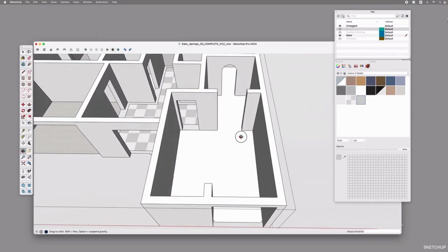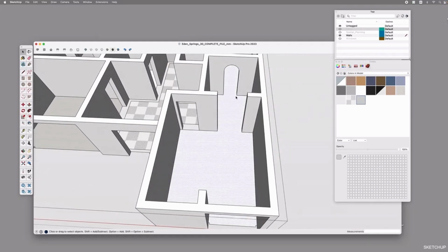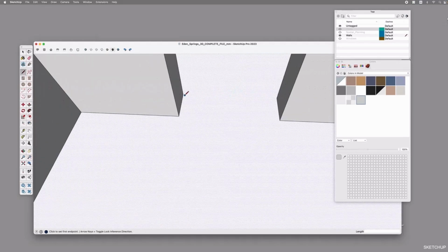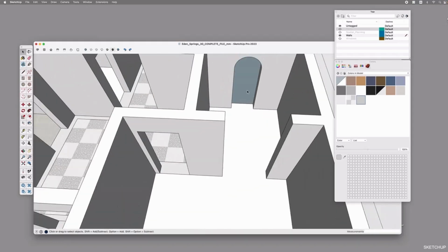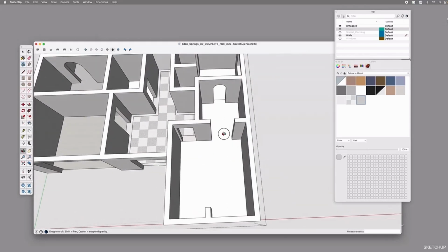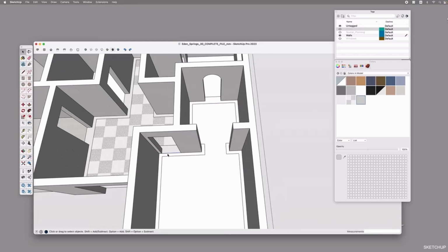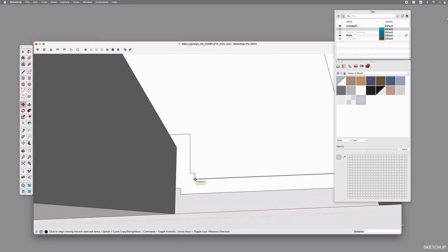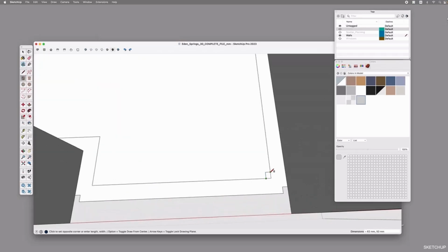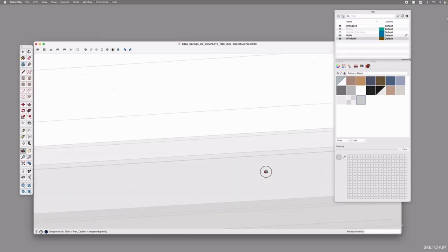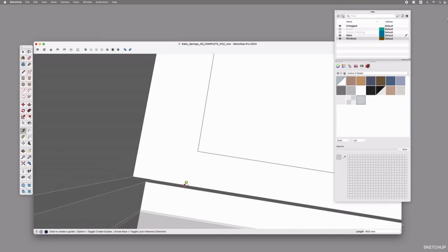In certain instances, SketchUp will automatically enclose an open area when it senses collected lines. Should this occur, you can easily revert that process by deleting the generated surface. To validate the accuracy of your adjustments, turn on all necessary layers like the windows and doors.